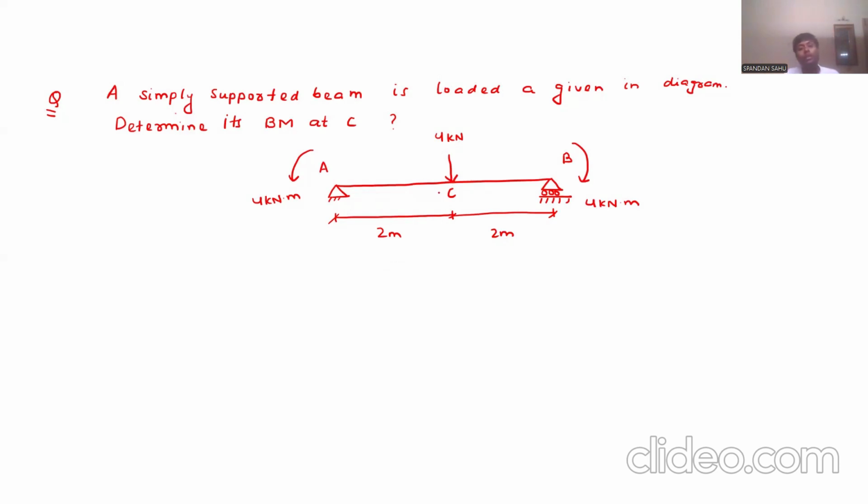So how to do this? First, step 1: calculate reactions at supports. How to do this? Just write the equations of equilibrium and you will get the support reactions.